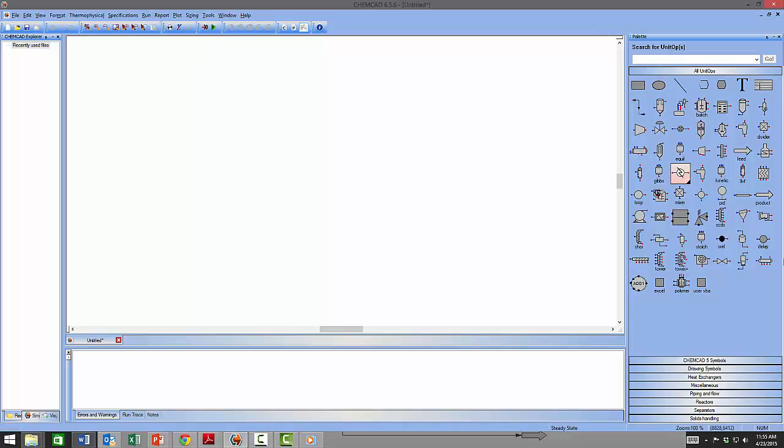Let's go back to building the flow sheet for our simulation project. We first need to introduce two feed streams, one for the process stream, that is the methanol and water vapor, and the other for the cooling water. We will just click once here on the feed stream to choose the type that is currently selected within the types of this particular unit op.